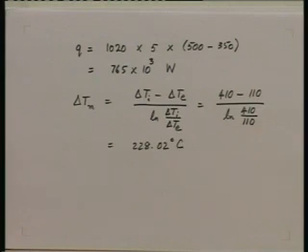Now, we are given the values of HH and HC. We are not told anything about fouling. So, we will have to make an assumption, first of all about fouling, and secondly about the thermal resistance B by K. We are not told anything about that. But notice the values of HH and HC are low. They are low because we have got air flowing as the heat transfer medium. So, values of HH and HC are bound to be of the order of 50, 60, 100, something like that, not going to be in thousands with air flows.